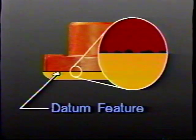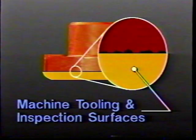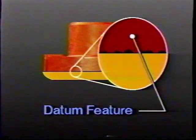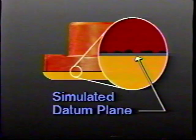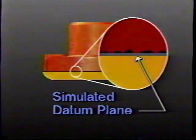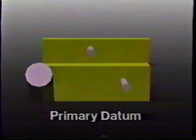Magnified, you can see that the surface of a datum feature is irregular and imperfect. It would not serve as an accurate origin for measurement. Machine tooling and inspection surfaces, on the other hand, are considered to be perfect or exact. When in contact with a datum feature, they create a simulated datum plane from which more accurate measurements can be made. Usually, the largest and most important surface or feature that affects the part's function is used to establish the primary datum. There must be 3 or more points of contact between the part surface or feature and the machine tooling or inspection surface in order to establish the primary datum.